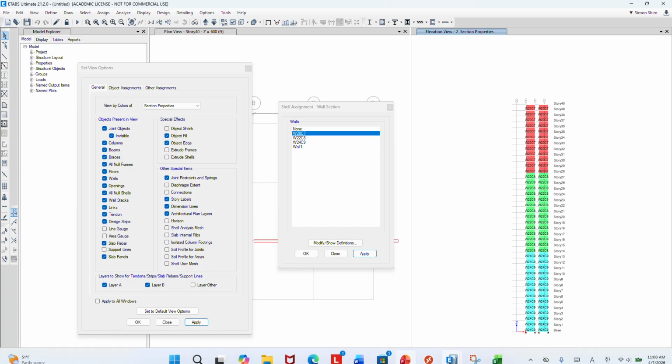All right, so this is an exercise, you're going to do it. It's sizing up, right? Because of stiffness. So what I'm just explaining is something ETABS or every software, you need to take this action. First of all, initially you set up geometry. Now you have the wind load and deflection check.